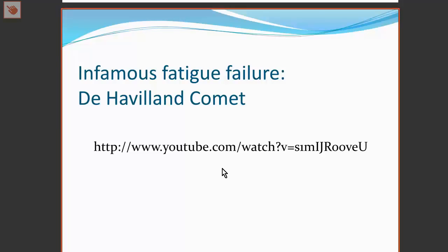I would really encourage you to watch this video. It's about one of the first commercial jetliners built by de Havilland in the 1950s. It became a great commercial success, but then there were a series of accidents, mysterious accidents. The planes were falling out of the sky, and intensive tests were done, and it was realized then that the fuselage was failing due to fatigue, due to a particular design flaw and installation flaw with the windows.